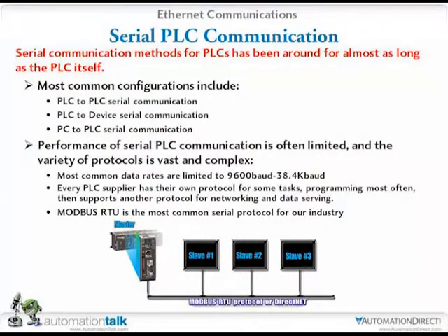We're probably going to hit some of this stuff again and again. Serial PLC communications was the original. Ethernet didn't come out until later. I won't jump that far ahead. But most common configurations include PLC to PLC, PLC to device serial, and then PC to PLC. And trust me, you can still use standard serial communications to your PC for programming. It's an easy way to go. And some of our PLCs, that's all they support. Say the 105, that's all it has.